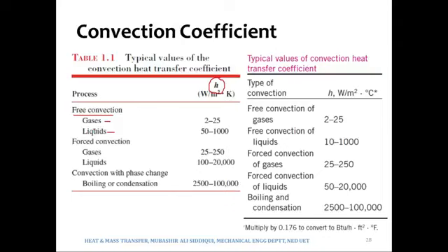Because by definition, specific heat is the amount of energy that would be absorbed, for example, by a fluid to bring a change in unit mass by 1 degree Celsius or 1 Kelvin. So where there are liquids involved in heat transfer, they would be able to take away more energy, to absorb more energy, to convect more energy as compared to the gases.